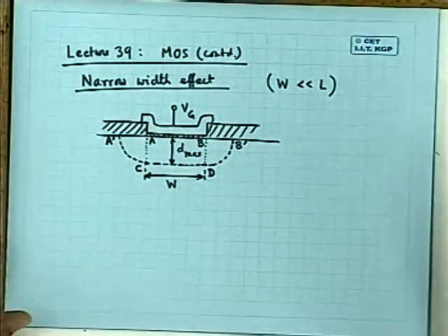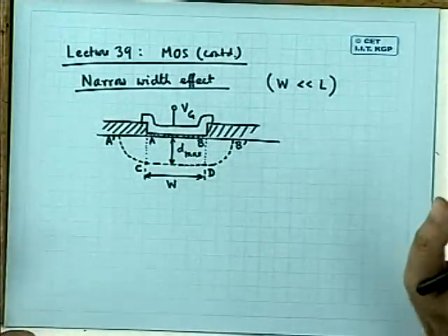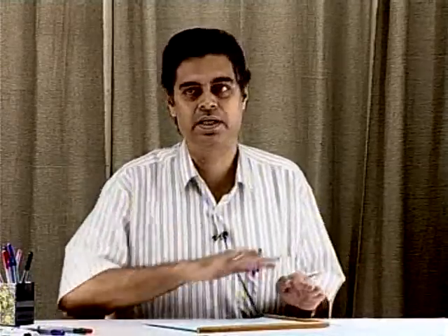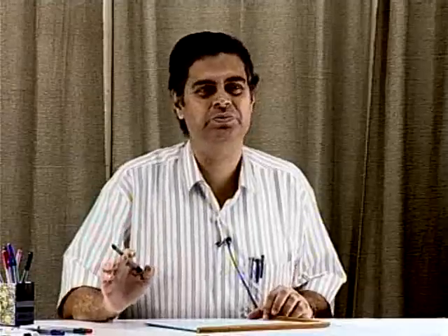I do not know whether the MOS technology has been taught to the MTech VLSI technology course, but here is a standard practice that a field implant is carried out to remove the presence of inversion layer from the surrounding region. But let us ignore all these things. Let us assume that it is an ideal, called flat band case, ideal flat band case.